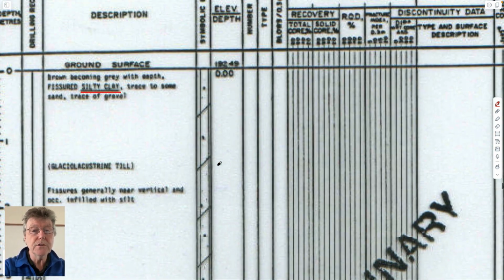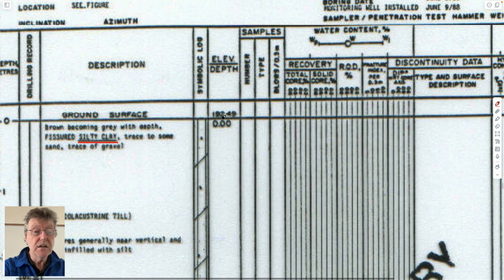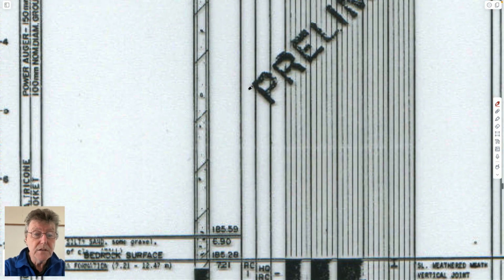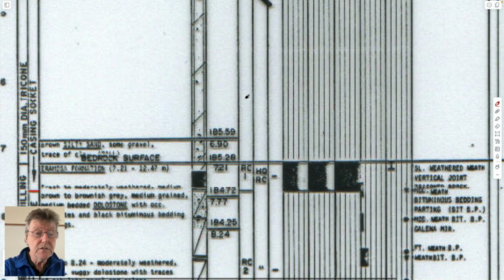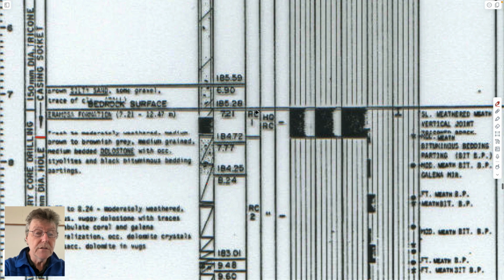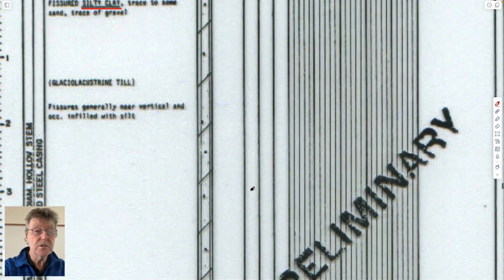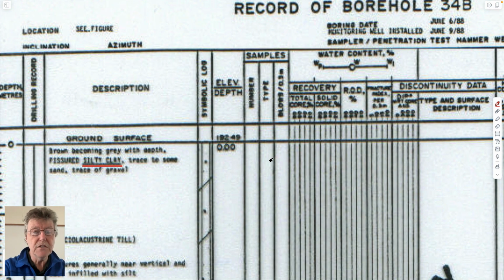You provide also some other information. Everything's done with depth. You'd record whether you're taking samples in the soil. So it looks like no samples are taken in the soil here, but in the rock you've got rock core defined, and that would be boxed just like we saw on the core shed. And you'd also write down any information from the other soil samples that you might take.